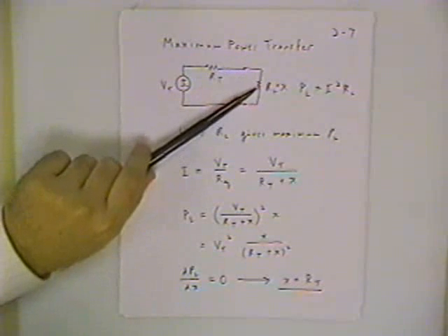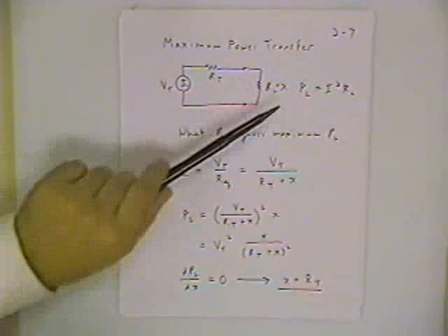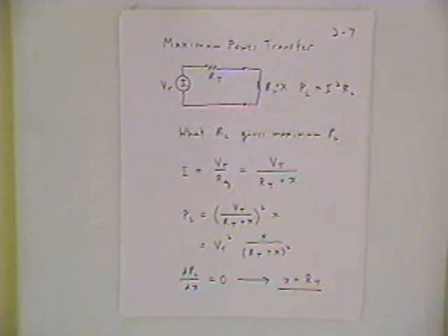So at either extreme, either a load resistor that's too small or too large, I'm going to have less than the optimum amount of power. You get the maximum power, though, at the intermediate value of Thevenin resistance. So that's something to keep in mind, and we'll actually visit that again with an AC circuit equivalent for maximum power transfer with AC circuits. But for a DC circuit, you get the maximum power transfer to the load by setting the load resistance equal to the Thevenin resistance.